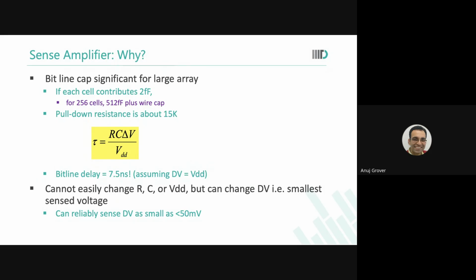Yes. Now, all the bit lines don't need to discharge to VDD by 2 or lower. They can discharge to only a small value delta V, which could be much smaller than VDD by 2. And therefore, the bit line capacitance will have less discharge, so less precharge power is required at the end of the cycle, so you save power.